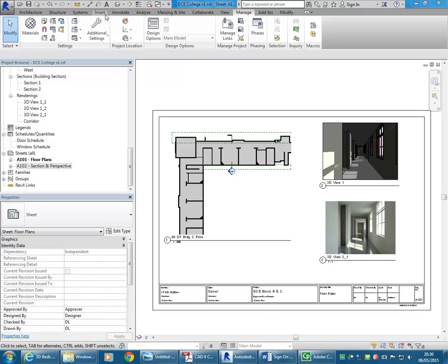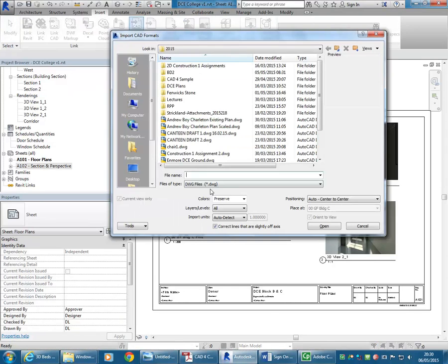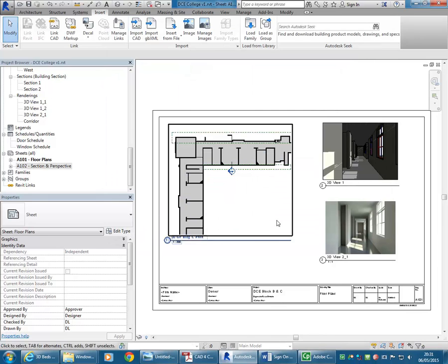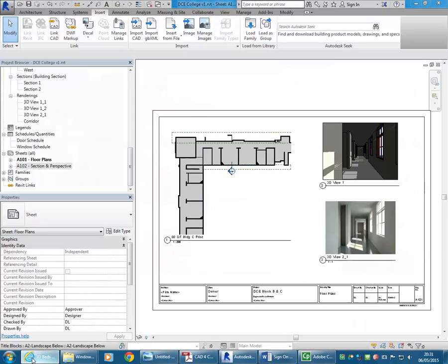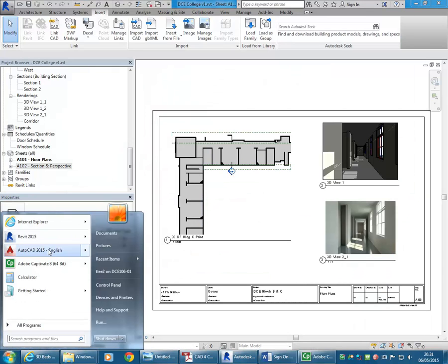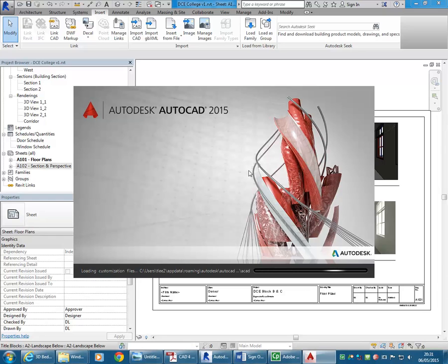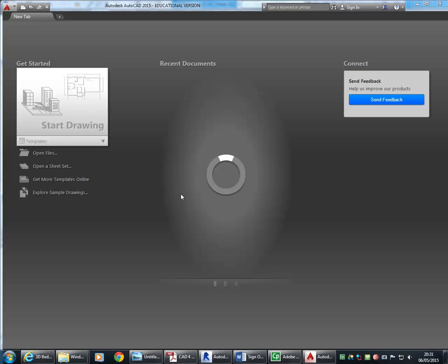So when you go to import into Revit, you'll see you only have these options for 3D files. So they're all basically CAD formats, except for SketchUp. So you can bring SketchUp files straight into Revit, and that's the first thing I'd try if you want to bring a SketchUp file in. There's another way, if you can't get it to work that way, it's mainly the materials that will cause problems, and so you can try a roundabout way going into 3ds Max first and then into AutoCAD and back into Revit. But otherwise, if it's any of those more general 3D formats like 3ds, you can just bring them straight